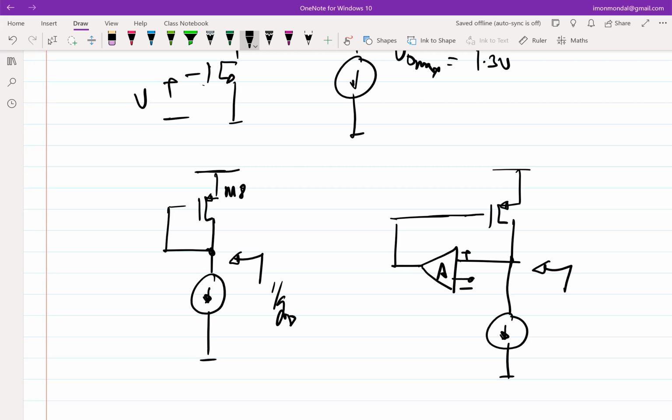That's the ideal voltage gain of it. It's still the same, is it? On the left hand side structure. How did you find out? You apply a test voltage, V test. What will be the voltage here? So what will be the current? Gm into V test into A, right? So what is the output impedance? 1 by Gm into A. So the output impedance goes down by a factor of the gain, 1 over A times Gm.